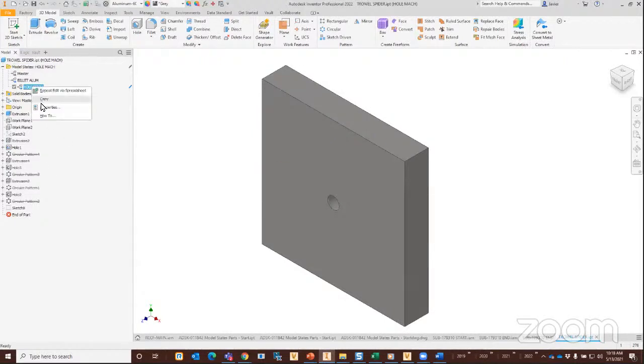And next thing I'm going to do is I'm going to go ahead and copy this. Okay, so I'm going to represent the rest of my machining features in just a couple features here, but I'm going to go ahead and call this one bore. Where maybe I'll bore out that hole at the center. Okay, and I think that shows up right here. So you've got to remember to make it active.